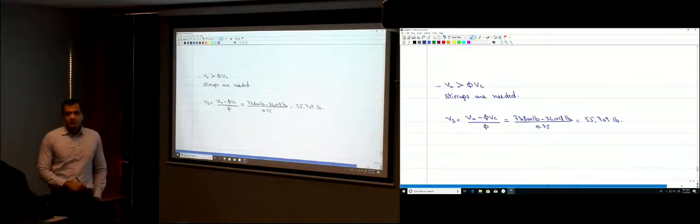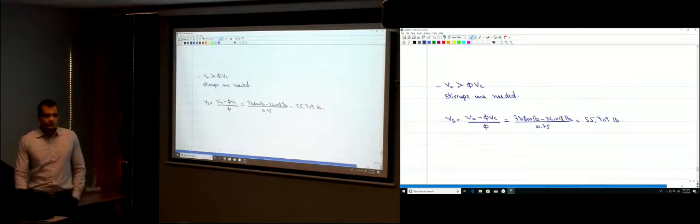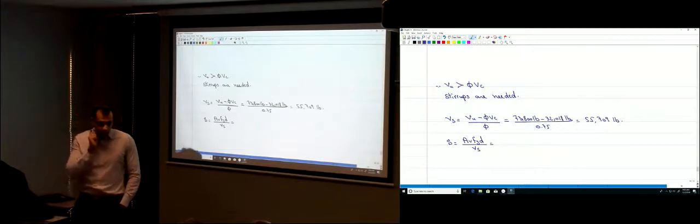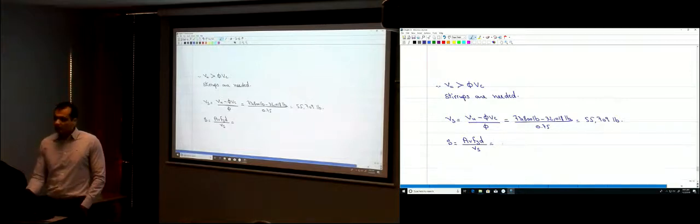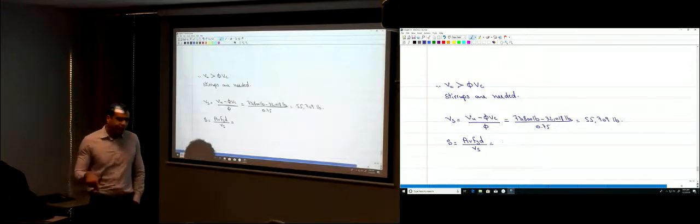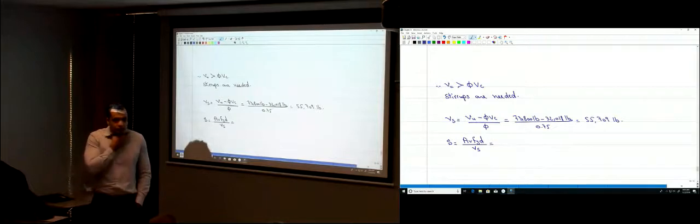If this is the shear force that should be resisted by the stirrups, how much is the stirrup spacing? You have the equation. S, the spacing, is Av fy d divided by Vs. That's the required spacing for the stirrups. How much is Av? I have U-shaped number 3 bars. That's what I'm using for my stirrups.